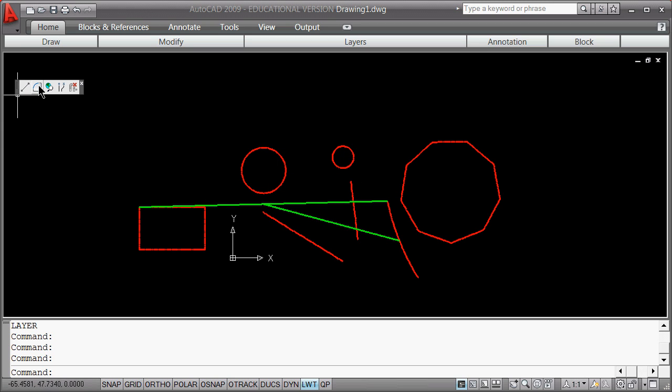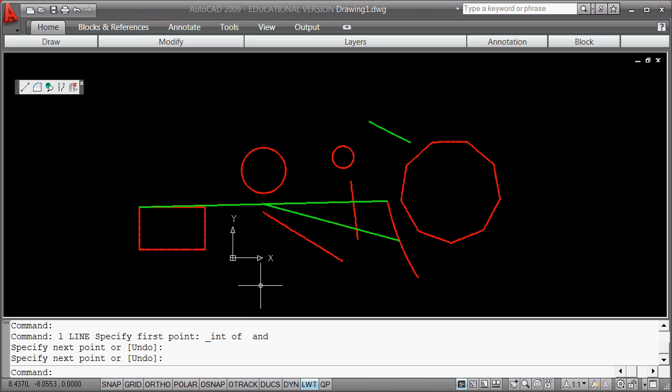I'm going to say L for line, shift right click, intersection. Obviously things have intersections when they connect to each other and run into each other. Polylines have, now that's pretty, if you notice you have the object snap tracking here, it's trying to find this kind of general intersection of that and that. So I don't necessarily like that command. I mean, I like the intersection, but the fact that it's trying to force more on you than you're asking for. But I'll do that again.